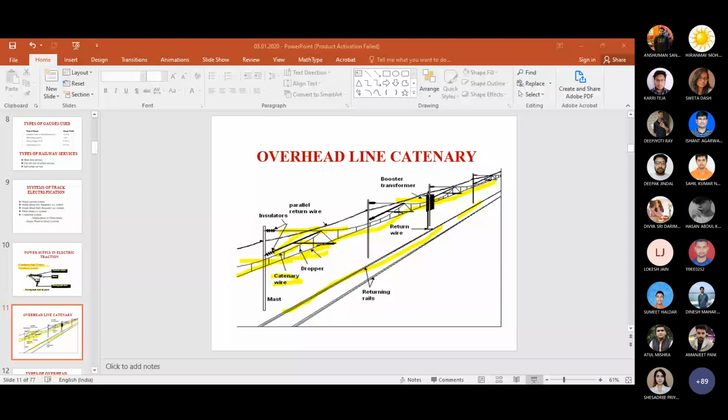Most cities right now are using underground cable, but in most places in India you can still see street connections, with different wires near your RCC pole. The phases are connected according to load balancing. Some of your houses are connected to the R phase as well as neutral, and some houses may be connected to the Y phase as well as neutral, like that.